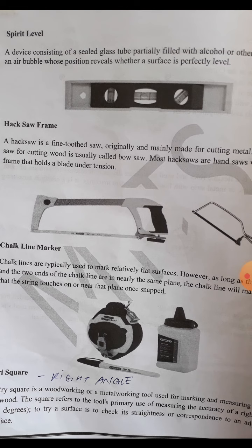The small hacksaw frame you can use in gland and termination time, glanding time, cutting the outside of the cable insulation. And the big hacksaw frame you can use for small cable tray, trunking, GI conduit or EMT conduit cutting.